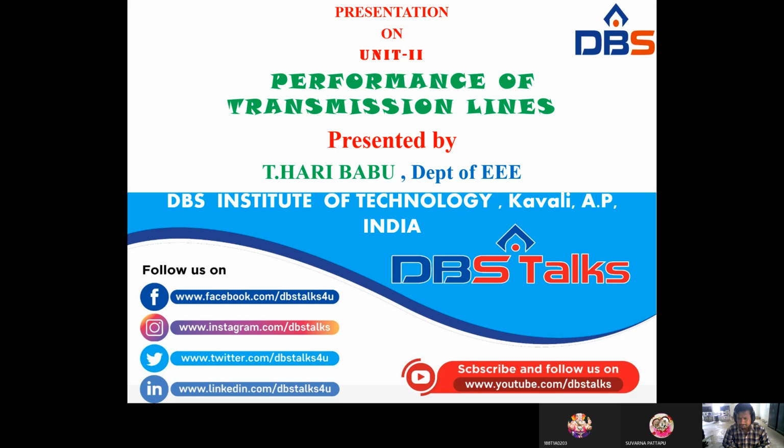So VS is equal to A VR plus B IR, IS is equal to C VR plus D IR. That means we know the receiving end voltage and the receiving end current. By using these two values, you have to determine the sending end voltage and sending end current with the help of ABCD constants. Why? Because we know the receiving end.